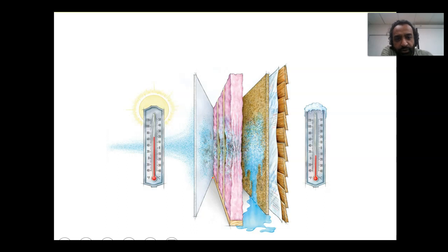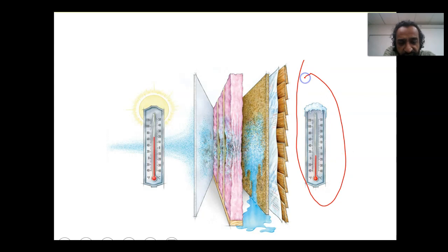So this shows you how the barrier acts. This is the outside here. It is freezing, and inside we have this barrier over here. So the water will go into the wood panel and drip, and this is where the moisture goes in, and it's going to fill your insulation and your wood panel, and eventually it'll cause you some problems. So water does go through the wood panel. So probably you want to have barriers on both sides.